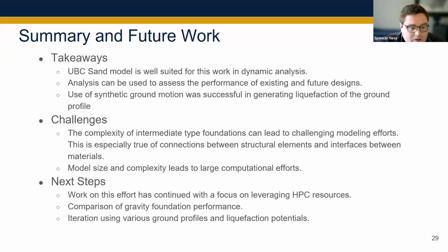Some of the challenges we were running into are that, as I mentioned, particularly with these intermediate type foundations, there are lots of challenging structural elements that challenge the modeling effort, where you really need to understand how the structure is designed and how it is supposed to perform, particularly at these connections between the ground anchors and the upper cap.